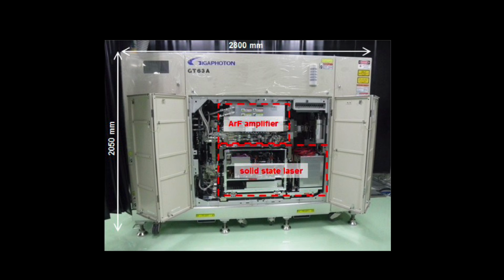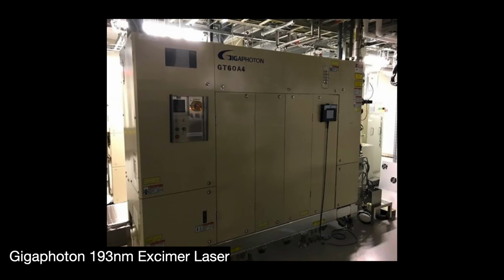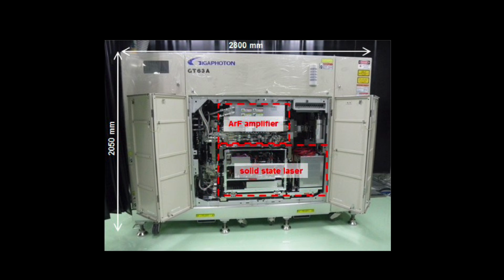These sophisticated lasers replaced the old i-line lamps companies used for lithography, unlocking a vast new green field for lithographic improvements. In 1999, the industry started using 248nm krypton fluoride lasers for their leading-edge process node at the time, 180 nanometers. 2 years later, in 2001, 193nm argon fluoride lasers, I will always call them ArF, entered the market. These are substantially similar to their 248nm predecessors. These enabled Intel to rapidly commercialize new technology nodes at 3-year intervals, progressively reducing their transistor's smallest dimension 30% each time.